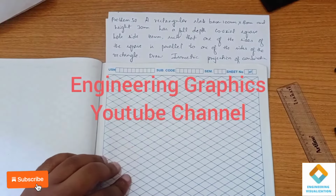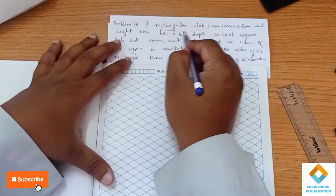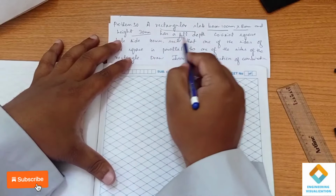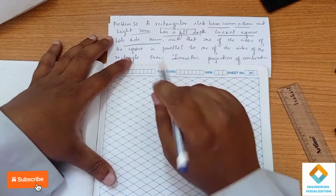We see problem number 50 from the CAD solution book in isometric. In this problem they have given a rectangular slab of side 100 into 80 and height 30 with a full depth coaxial square hole of side 40. So first we are going to construct the rectangular slab here.